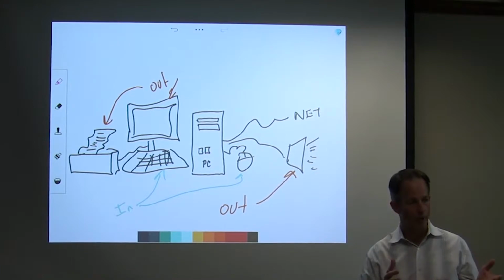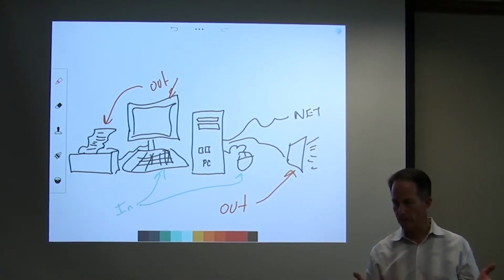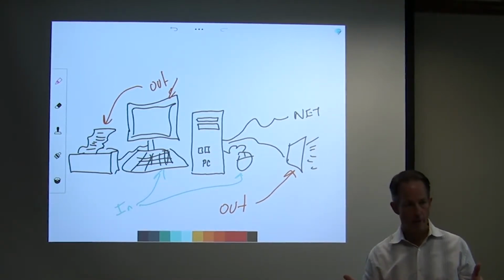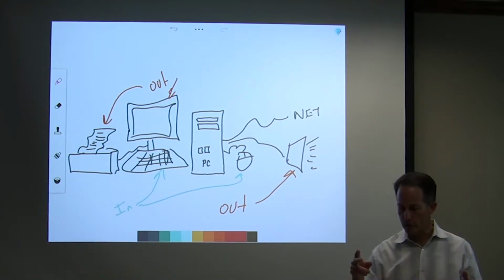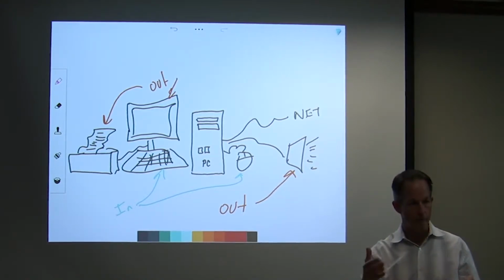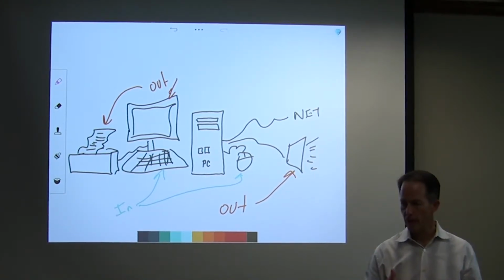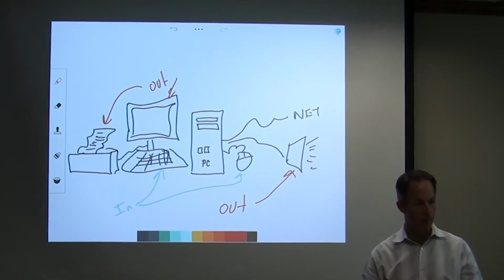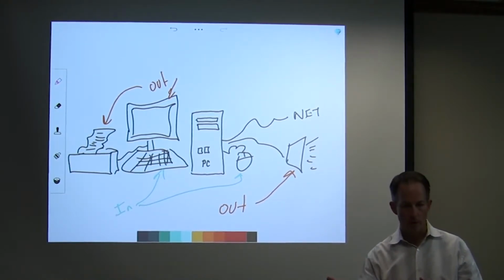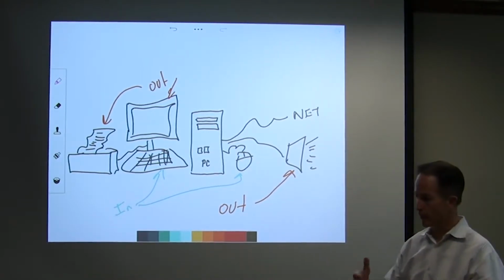Others are a powered output. They may be 24 volts. They may be 0 to 10 volts. Delta has 2 versions where 10 volts is on, 0 volts is off. A lot of controllers are 24 volts AC, 24 on, and then 0 for off. And so those would be how we would turn things on and off.